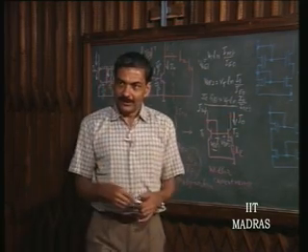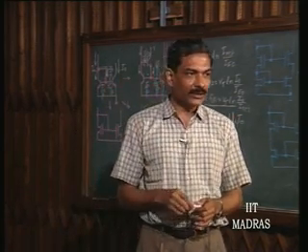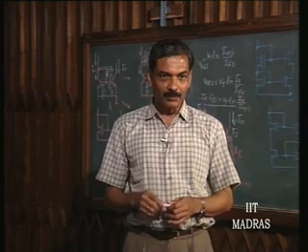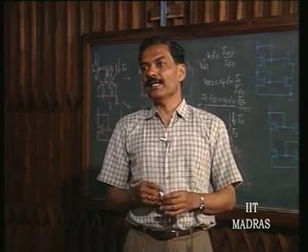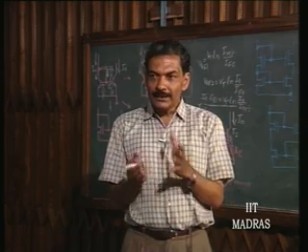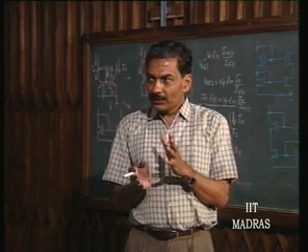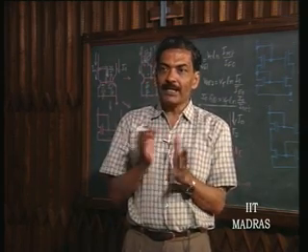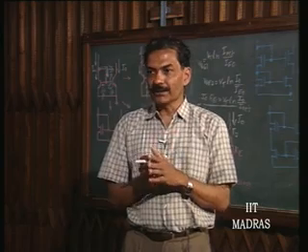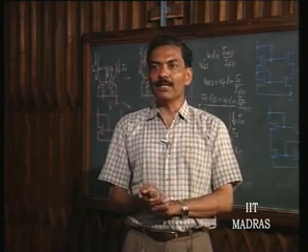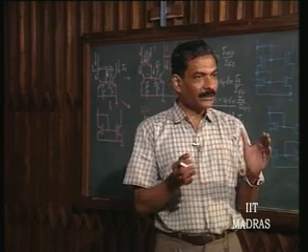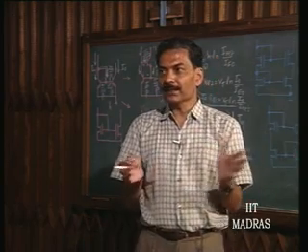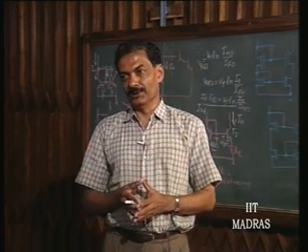Of course, this is a nonlinear equation which you have to solve in order to obtain value of I naught, but this is not the way IC designer is going to view it. IC designer wants to have an I naught which is very low compared to I reference. I reference may be of the order of milliamperes, which could be easily obtained by using voltages of the order of tens of volts and resistors of the order of kilo ohms.